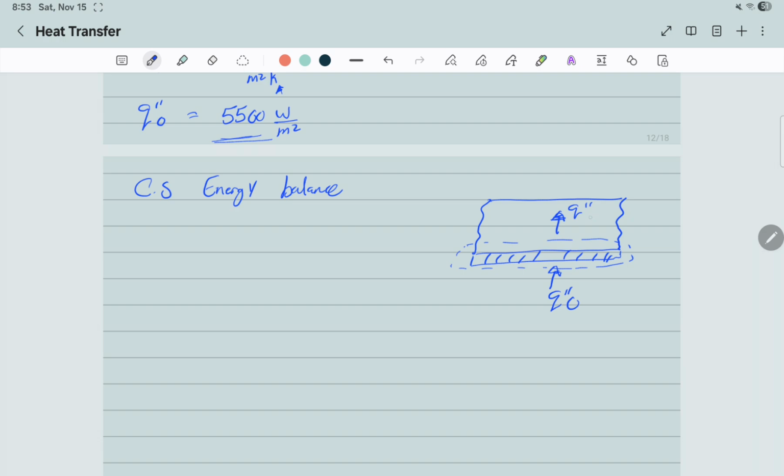And the heat flux leaving the bottom surface is conduction, because there's a metal surface there. There's no fluid, there's no air. Therefore, the initial heat flux equals the conduction heat flux, which equals KΔT over L.